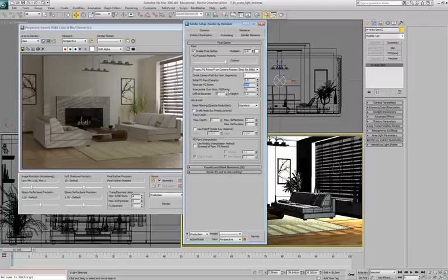The interpolate over number of final gather points is set at 30. If we want to manually work this value over, we can go down to our final gather point interpolation. Again, this is one of the older ways to do it. This is, again, Max taking control of it, gives us a number value that we can work with. Just because this works well with the scene, we're going to go ahead and go down here. We're going to take it off of the radius pixels, and we want the radius in world units. So we've got it at our units here. We're going to select on our radius and our minimum radius.